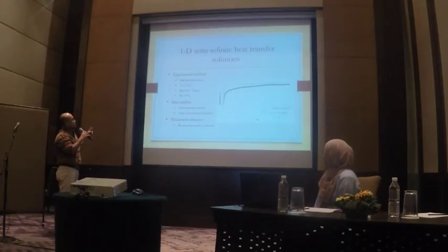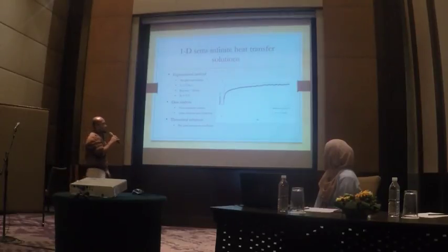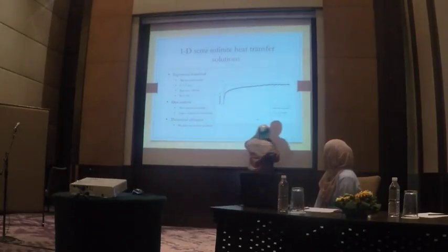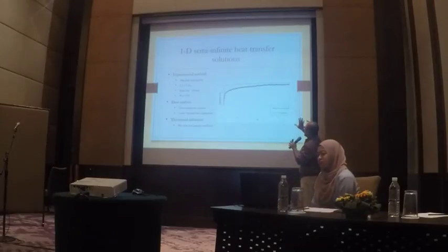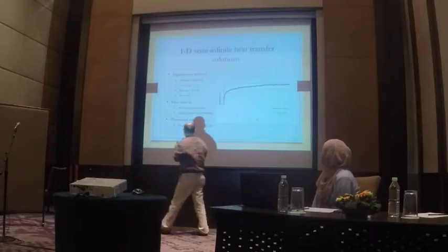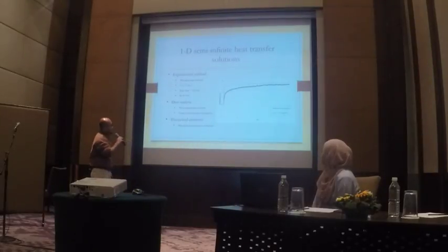So with a velocity of 27 meters per second, the experiment was conducted for quite long, which is half an hour, represented by Fourier number 0.95. The data analysis for the surface temperature will involve two solutions. One is the two temperature solution, and the other one is the Crank-Nicolson heat conduction. The reference will be from the flat plate heat transfer coefficient.